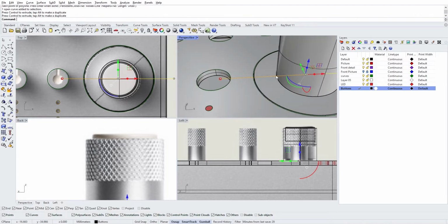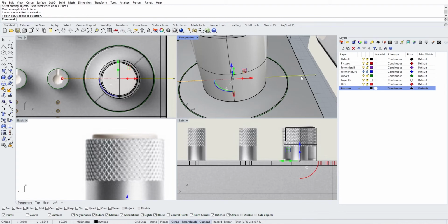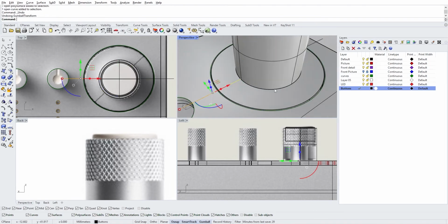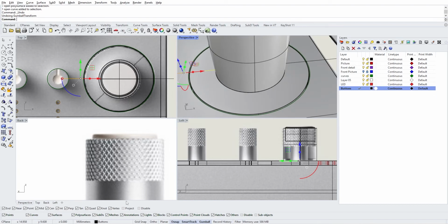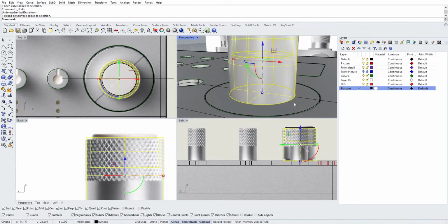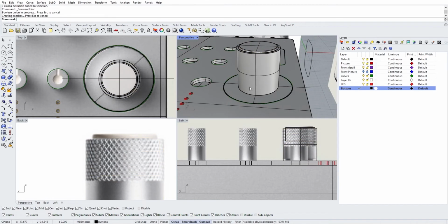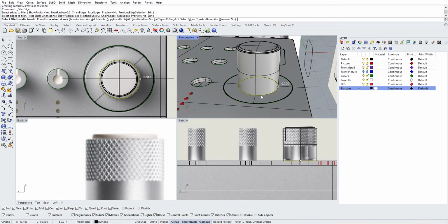Then maybe we can cut this line with that. So split this like this. So you have two curves. And then I think it's better to put the chamfer first here, actually. Let's join those two pieces here with the Boolean tool, then fillet, and here we can put, so at the moment it's 0.2.